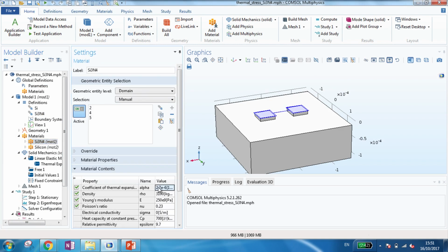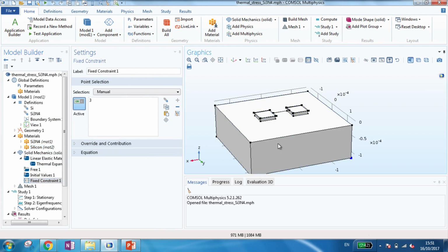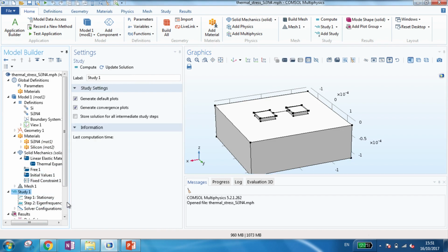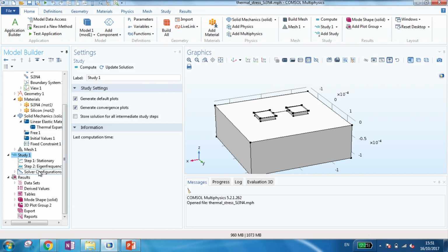And so you can see here nicely that obviously the stress in the silicon nitride thin film is different. Its color is different than the blue, which is 0 for silicon. If you calculate that, you can go there and calculate how much stress you would get. You can also check that your frequency is like a double clamped beam, higher frequency. This is easy. But what I want to emphasize is that by doing such a thing,